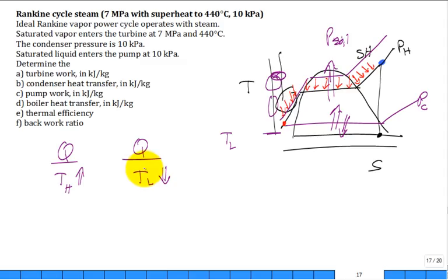How can you affect the condenser pressure? You're kind of stuck. You're dumping heat to the atmosphere. How hot is it outside? You can't get colder than that. Lake water. How hot is your lake water? You can't get colder than that.